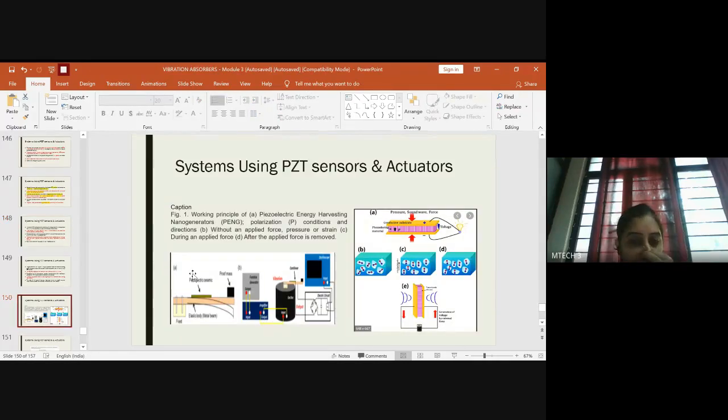So this cantilever has to be connected to the other electronic gadgets so that it will form a closed loop and it works systematically, because when the cantilever moves to and fro, vibration comes into picture. So when you have a vibration coming into picture, you should see what is the strain rate, whether vibration is too high or too low. If the strain rate is too high, first you have to fine tune the electromechanical shaker.